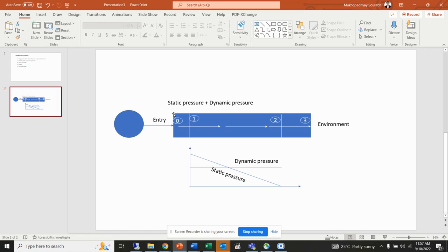And after that, next is the mass flow inlet. Mass flow inlet is similar to the velocity inlet. You are defining the mass flow traveling through this, and from there the code gets the flow velocity. But mass flow inlet is a little bit different from the velocity inlet. When the flow is compressible, that also depends on the geometrical shape and the size and diameter of the pipe. But for a simple case, let's start with the incompressible mass flow inlet.